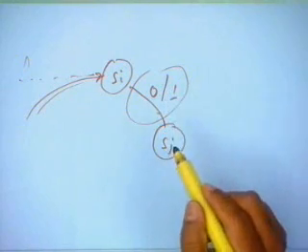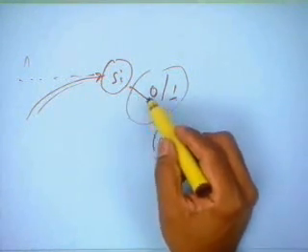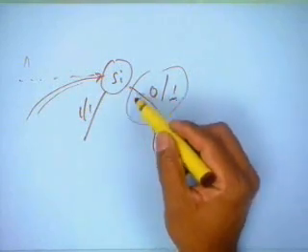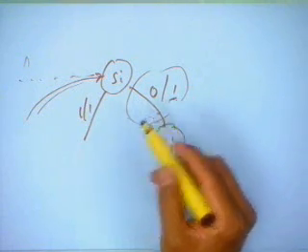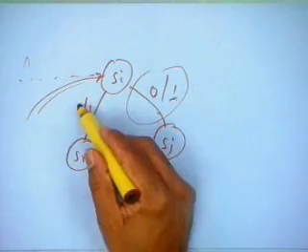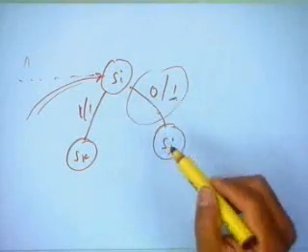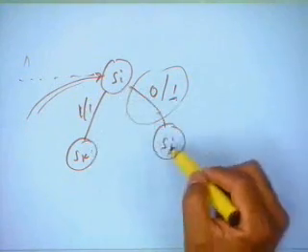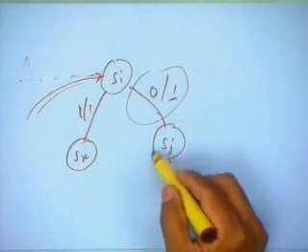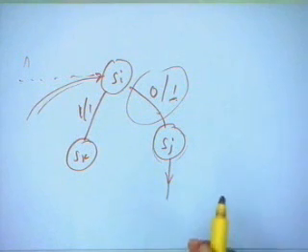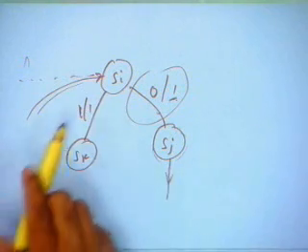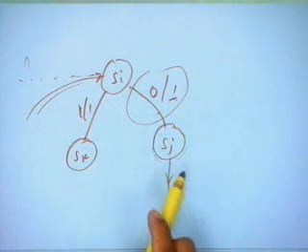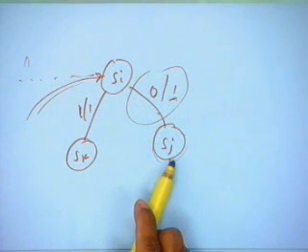When I apply the input, of course I can monitor the output, but this output may be the same not only for 0 input, but for 1 also. So I cannot still say with confidence that the transition is verified, because this Si may be going to Sk. Even at 0, the faulty machine may be going to Sk instead of Sj. So then I have to verify that I have reached state Sj. So three things have to be done: first, take the machine to the initial state to verify the transition, apply the inputs to perform the transition, then verify that the machine has reached the final state.